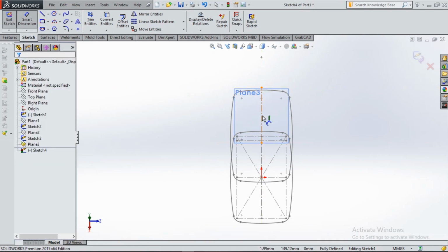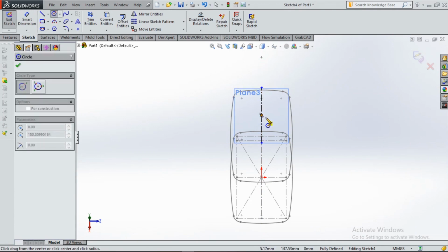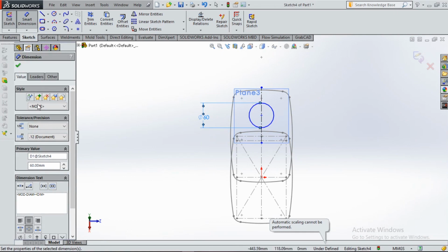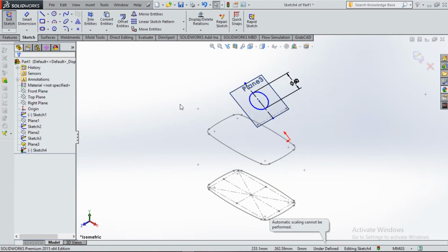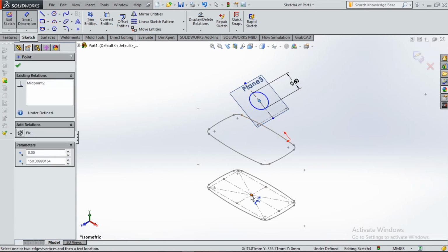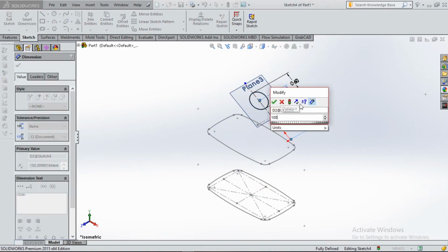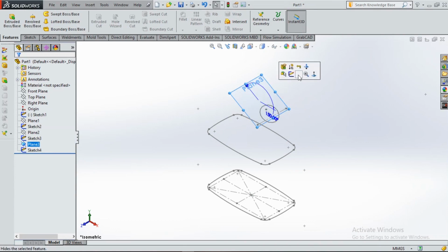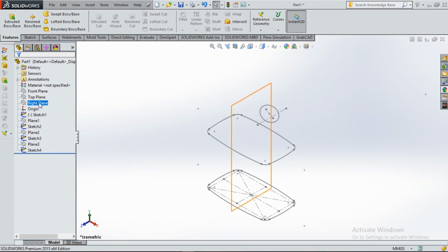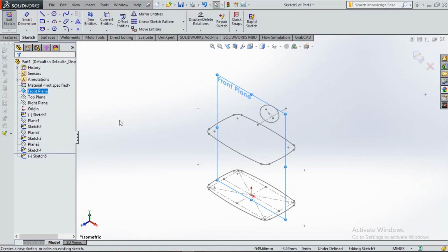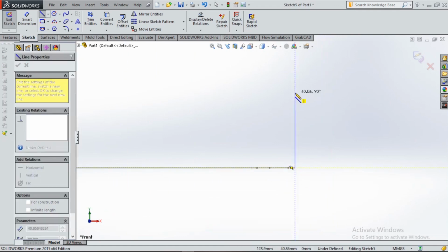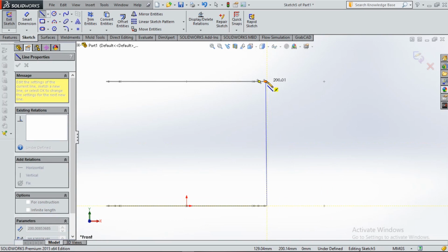Also, whenever you are making a sketch, be careful how you make that sketch relative to other sketches you have created. SolidWorks automatically adds relations to your sketches. If you make a sketch across a line, across any rectangle or any circle, a relation is automatically created, and sometimes when you need to add more relations, you get an overdefined situation. So you should be careful how you draw your sketches. If you know that you don't want any relation to be created between your present sketch and your previous sketch, you should try as much as you can to avoid crossing the path of your previous sketch.